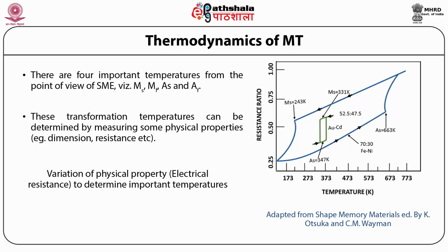On the other hand, when the transformation zone is large, the driving force is large, and the process is no longer reversible. These processes are called non-thermoelastic. The effects of SE and SME can be found only in thermoelastic transformations.